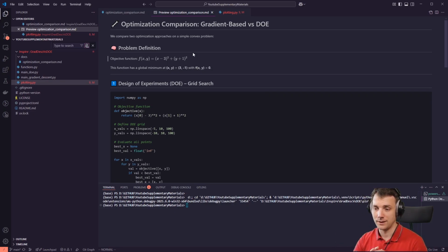All right, so you can think of optimization in that context like you have a bunch of design variables, in this case element densities, and you want to adapt the densities so that you have your function minimized, in this case compliance, or maximized stiffness, right?